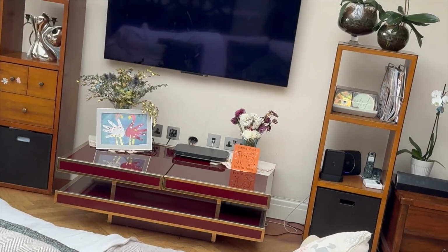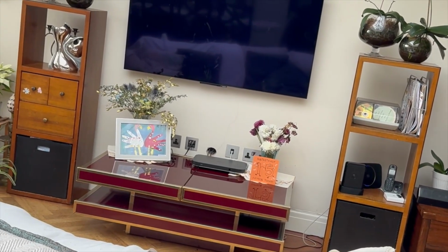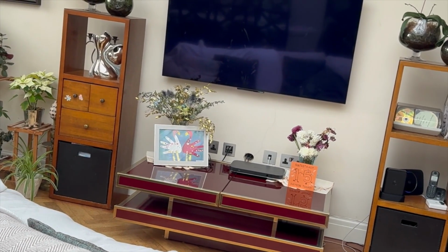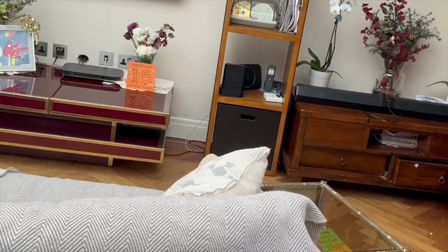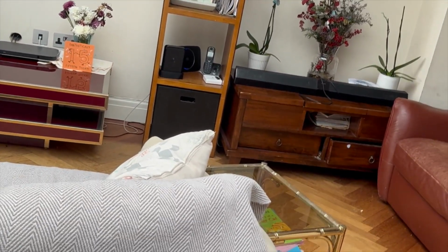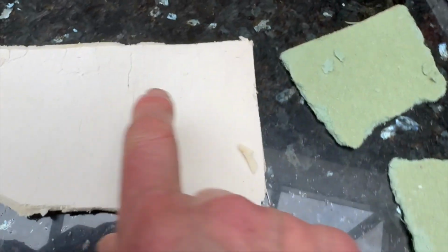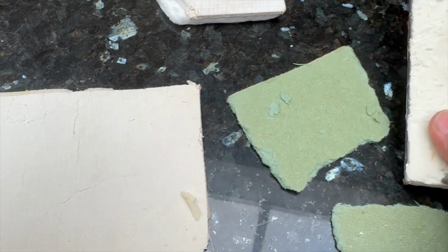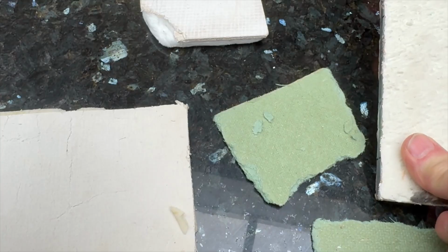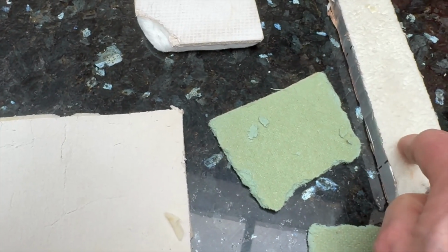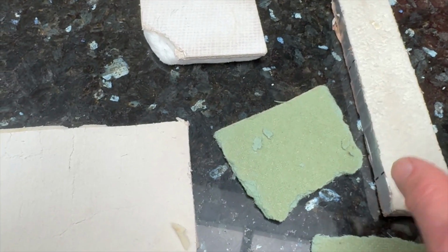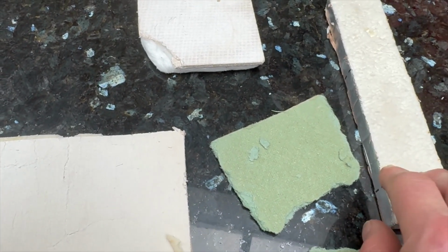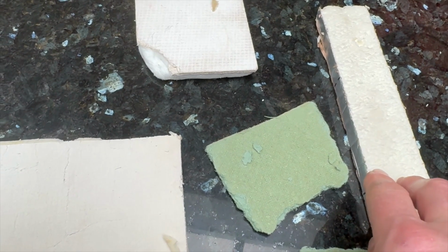I think your idea of putting a continuous flow extractor fan into the cupboard is a good one. Okay. But insulation, I'll show you different types of insulation now. So this is PIR, which is suitable for a property that doesn't have a suspended timber floor, which you don't. It's polyurethane. Celotex is a brand name for it.